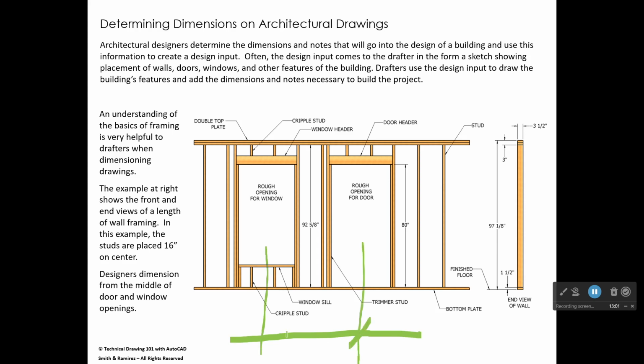So I'm going to just sketch a dimension on here. And then you tell the carpenters how wide the window or the door is. And what they will do is they will actually frame it wider than they need it to be. And this is called a rough opening.